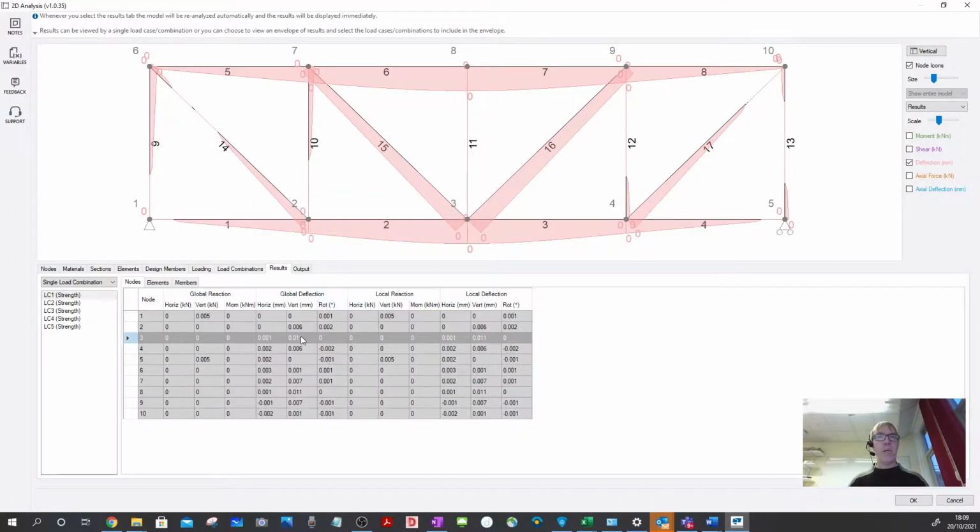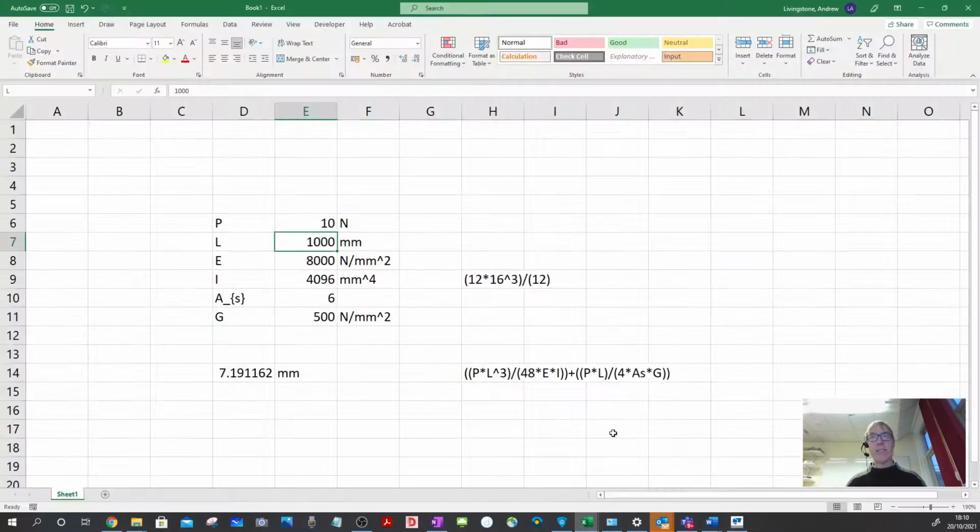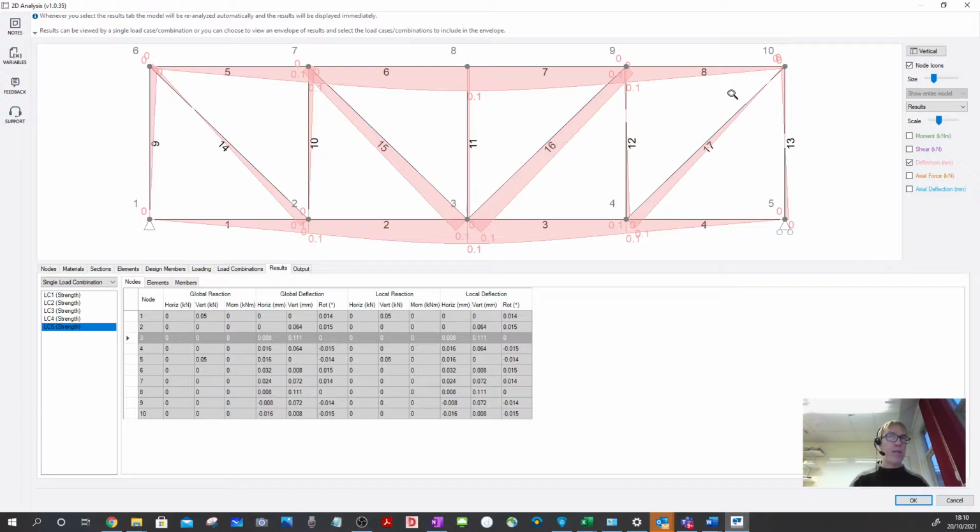We're now getting almost nothing at all. If we go to, even to the very top one, load case 5, our deflection here is 0.1 of a millimeter. Now that's in a truss type shape. We can have confidence this is correct because we've checked it against, when it was in a much simpler form, a simple hand calculation. So we know that the data in is valid. We've put it into a truss shape, so we know with confidence this is correct.